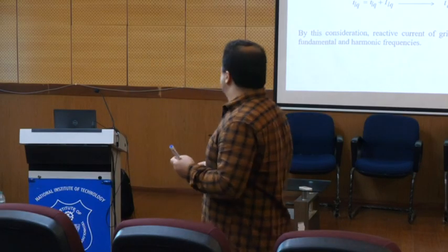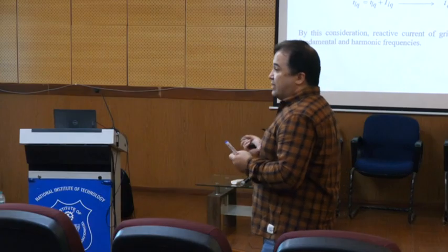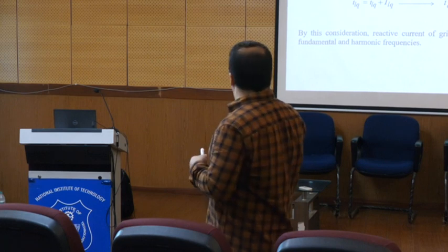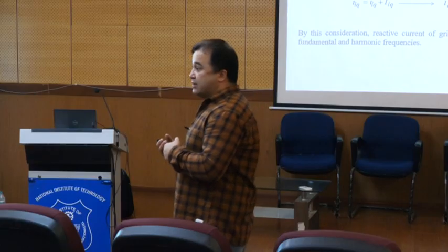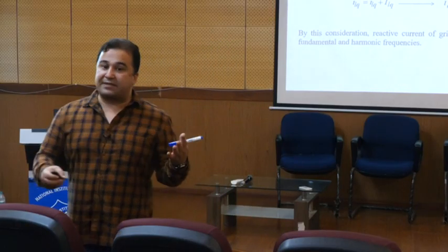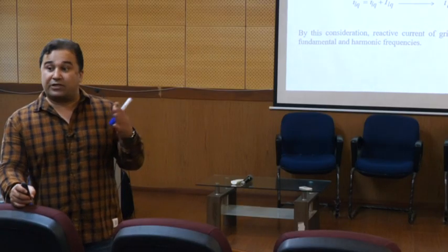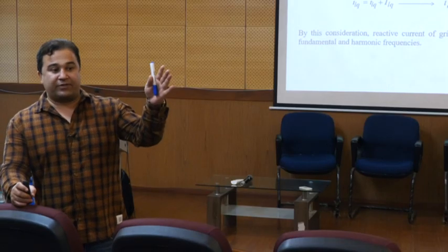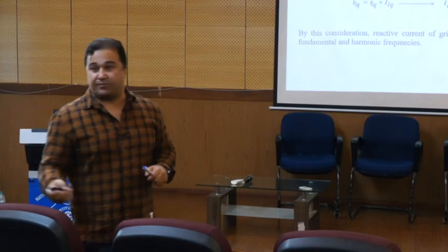For this case, the best is that we replace the reference value based on reactive power, both in harmonic and fundamental frequency. By this we can fix the power factor of the system at unit value. Any reactive power should be compensated, so this is different from the active power.